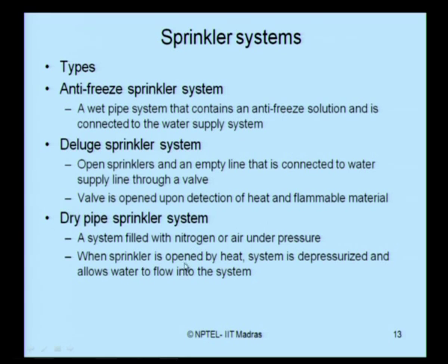When the sprinklers are opened by heat, or I should say excessive heat, then the system is automatically depressurized and therefore it allows water to flow into the system, because initially the system is filled with nitrogen gas under high pressure. When the sprinkler is opened by heat or senses excessive temperature, or senses a flame through a flame detector, then the system is suddenly depressurized and now the system will allow water to flow into the place where extinction has to take place.